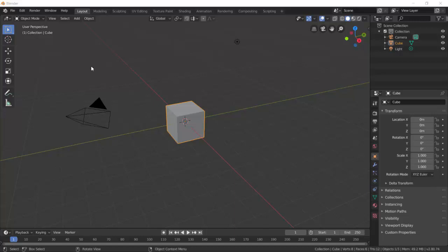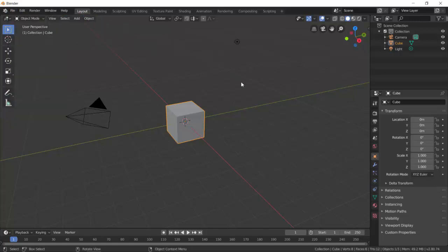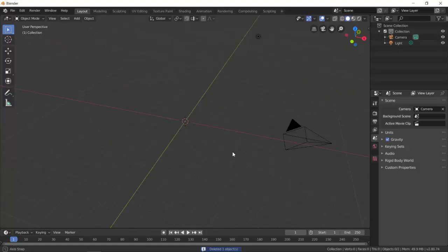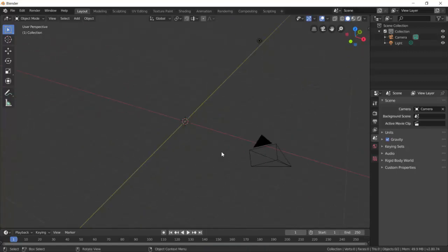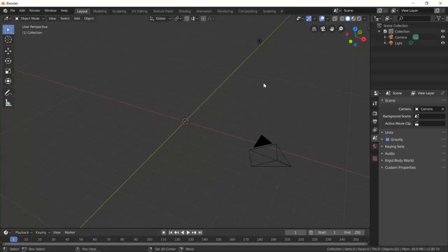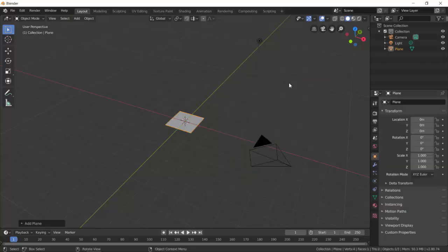So to begin with, like last week, we'll open Blender, File, New, and a General file. Now what we're going to start with today is deleting the cube, because we don't really need it there. And we're going to add in a plane. To add a plane, we can either go up to Add like last time, or the shortcut key is Shift A if you'd like, and that brings up the same menu, and Plane.